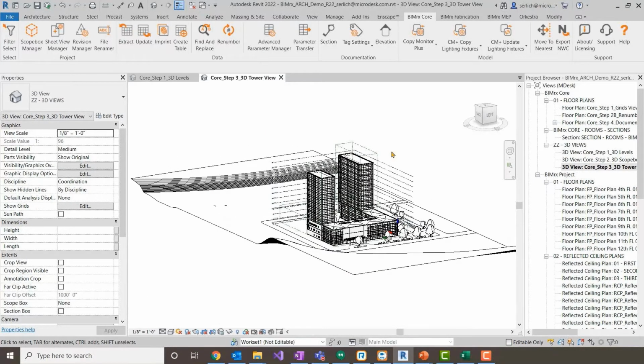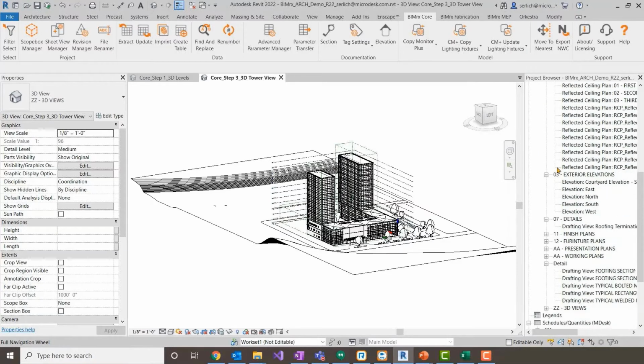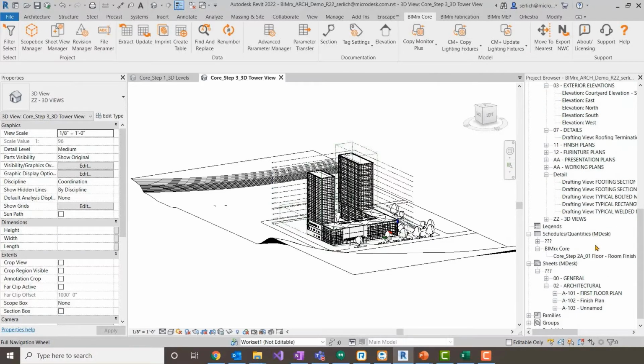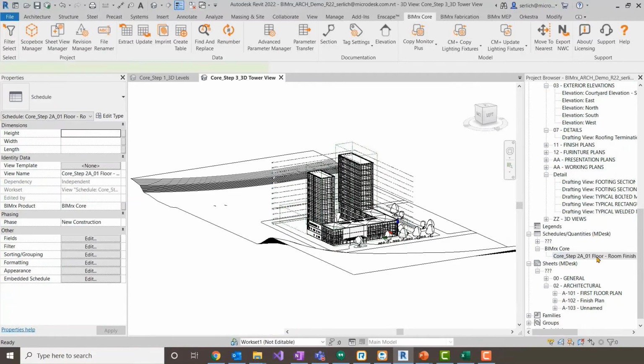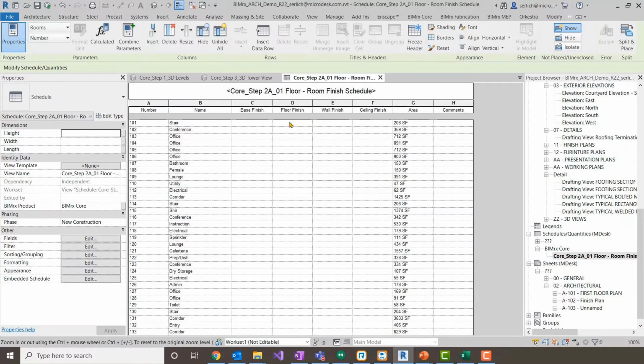model elements. And managing data is such a repetitive process within Revit. You must select each element and input all of that parametric information. And Revit makes this process a little bit easier by allowing us to create schedules. And here we have a room schedule where we need to update all the finishes, for example.